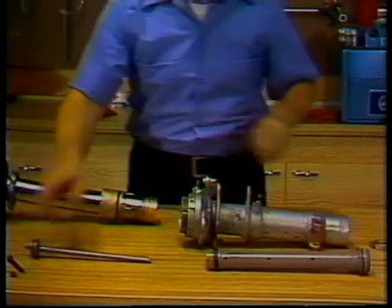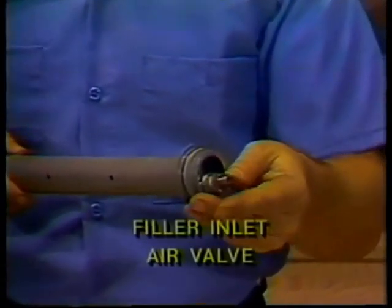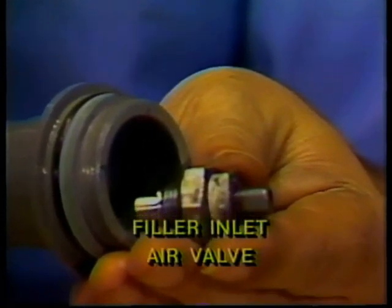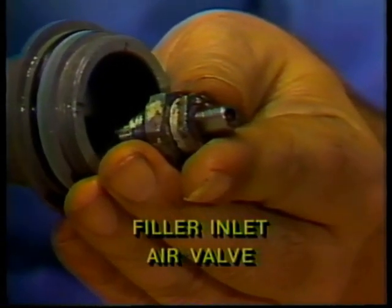A fitting consisting of a fluid filler inlet and an air valve assembly is located near the upper end of the strut and provides a means of filling the strut with hydraulic fluid and inflating it with air or nitrogen.